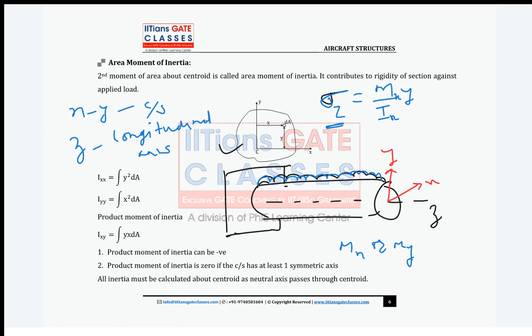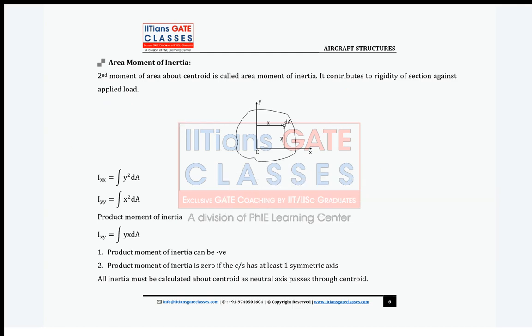Okay, we will discuss more when we move to unsymmetrical bending. Again, you guys have heard about compound bending, right? This sigma z can be Mx upon Ix into y plus, you can have, what guys, can anyone tell? It will be My upon Iy into x. Clear? This is known as compound bending, right? You have bending about both the cross sectional axes. Okay, so that also we will discuss and we will understand how these are coming.